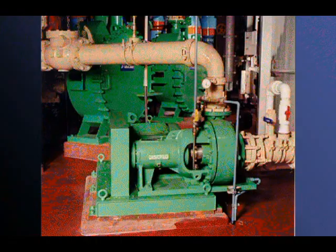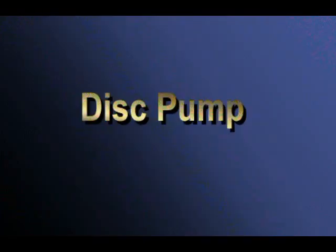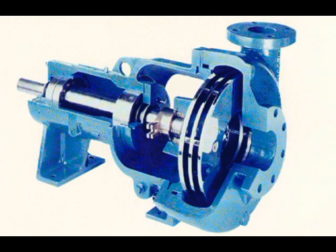A type of pump that operates by a mechanism similar to that of centrifugal pumps is the disc pump. The mechanism by which these pumps move fluids is boundary layer viscous drag. Fluid enters the pump and molecules adhere to the surface of the two discs. This layer provides a molecular buffer between the fluid and the disc's surface. As the discs rotate, energy is transferred to the fluid layer by layer, and the fluid is pulled through the pump.